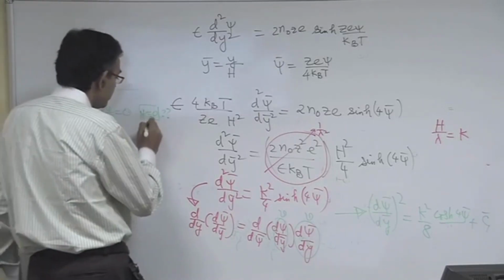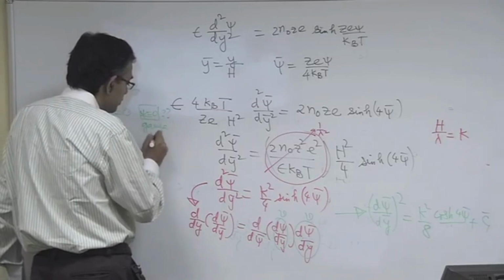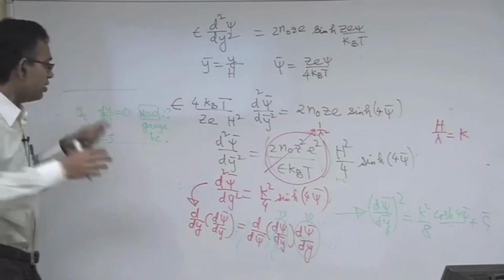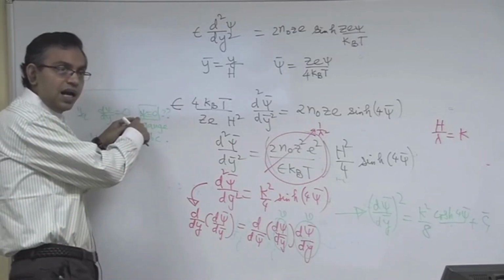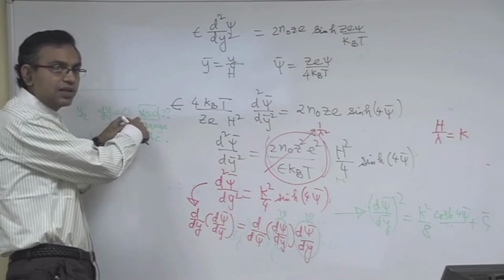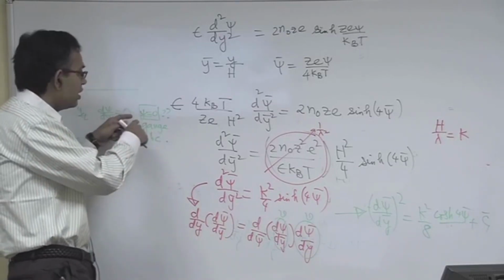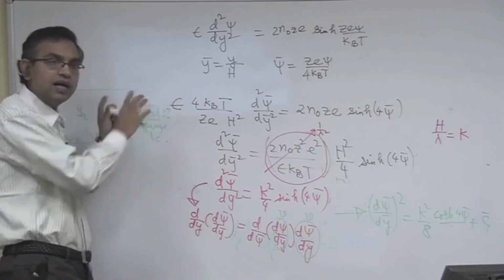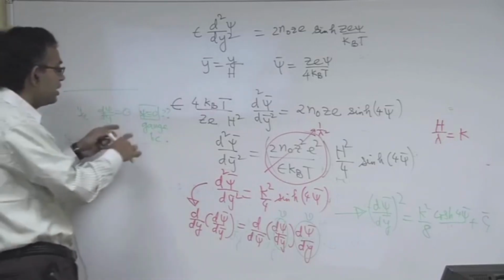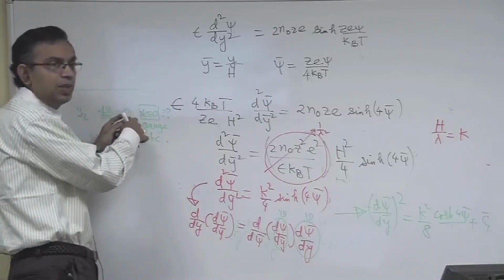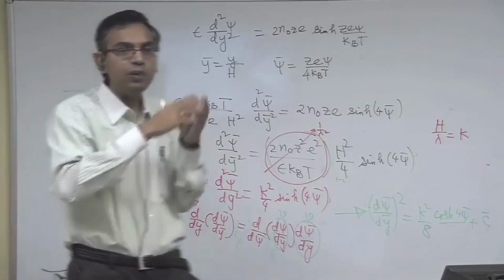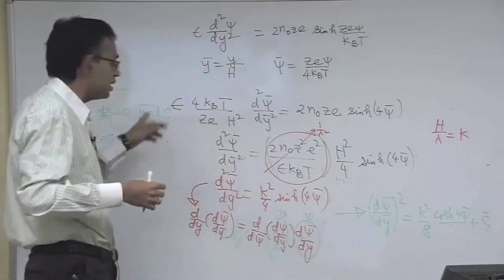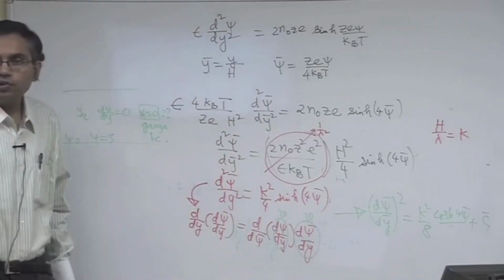So what is this? Basically all the potentials are relative. So there is a center line potential, and relative to the center line potential you are finding all other potentials. So you can set the reference potential as the center line potential, with the reference equal to 0, that is all. That does not mean that you are using it as an additional independent boundary condition. It is just like if you use P equal to P atmosphere to calculate the gauge pressure, similarly it is a gauge boundary condition based on which you calculate the potential distribution.